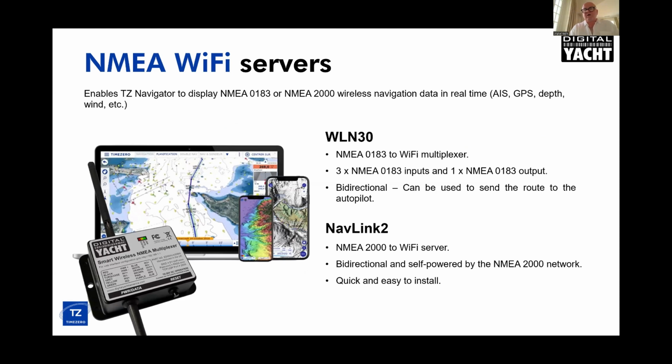If you want to use Wi-Fi, we do two products. We do a 3-input NMEA 0183 device, so you can put AIS, GPS, and instrument data. It combines all that data, so it puts it all together into one string and sends it out over the Wi-Fi link. It also allows bidirectional communication. So if you create a route or an autopilot link in TimeZero, it will send the data back, and TimeZero can then control the autopilot as well.